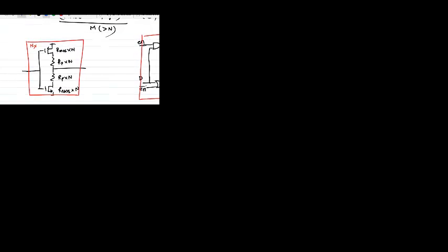Okay. Then let's look at what is the maximum swing which you can see in the PMOS output driver. So just look at this example. So this is VDD TX, right? So the output swing, this is called a high swing because you are basically connecting to the supply VDD. It gives you VDD transmitter by 2, right? So if I say V out,